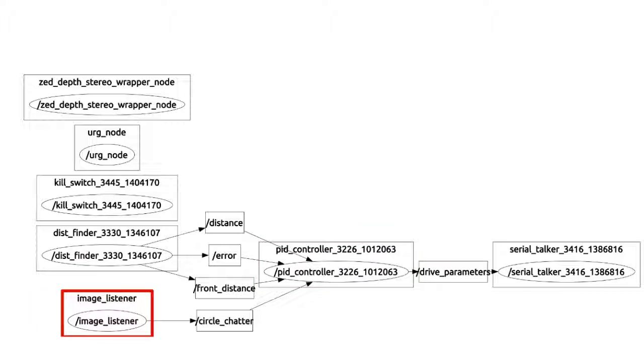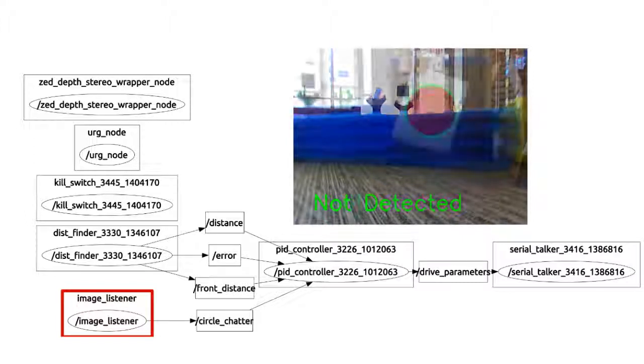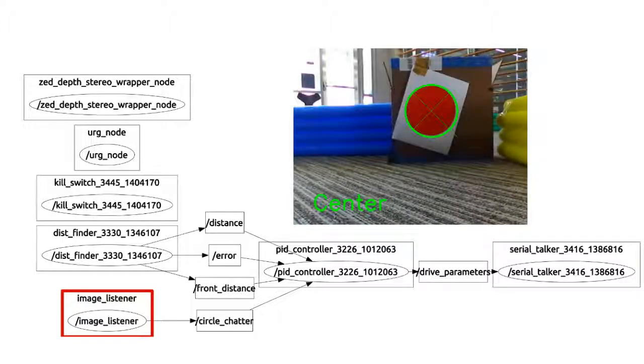The color node receives a frame from the ZED camera node. Each frame is processed to detect the presence or the absence of red circles. The data is transferred to the controller as a string. If there is no circle detected, the data contains a string value saying "nothing detected." Otherwise, it would contain the radius of the circle that was detected in that frame.